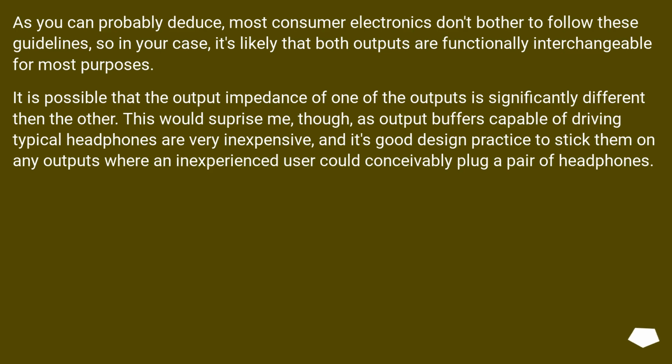As you can probably deduce, most consumer electronics don't bother to follow these guidelines, so in your case, it's likely that both outputs are functionally interchangeable for most purposes. It is possible that the output impedance of one of the outputs is significantly different than the other. This would surprise me, though, as output buffers capable of driving typical headphones are very inexpensive, and it's good design practice to stick them on any outputs where an inexperienced user could conceivably plug a pair of headphones.